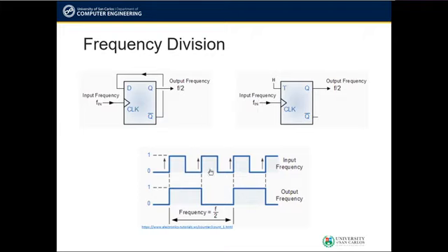Let's say, for example, that this is a clock signal that you want to divide or decrease. If you input this clock signal to the flip-flop clock inputs here and here, the clock output frequency taken from the D flip-flop here and the T flip-flop here will be divided by 2, which will now look like this.